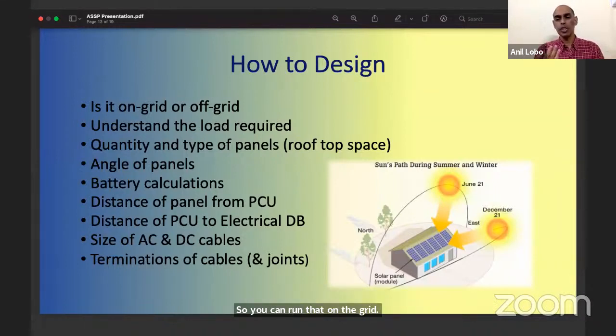But yes, you're going to use your washing machine almost on a daily basis. You will have your microwave, your induction cooker, you might have your water pump, your fans, your lights, your TV, your computers and so forth running on the battery even at night time. So that is when you look at the battery calculation. Plus, if you're going with a hybrid system, you can ensure that if the load exceeds your design capacity, you pull in power from the grid. This way you don't have to go with a large battery backup. The battery is for when the main grid fails, so you can use your battery in the night or in the daytime to get power for critical equipment.